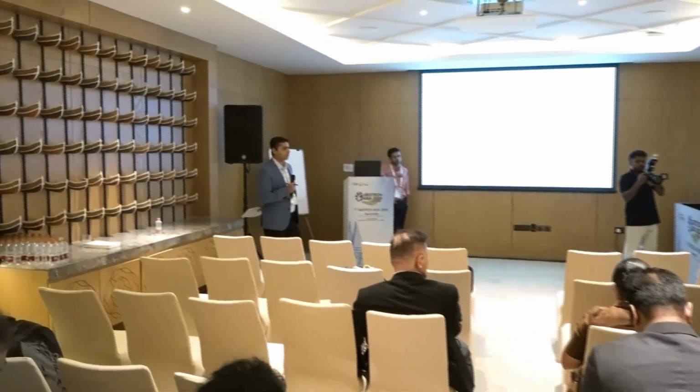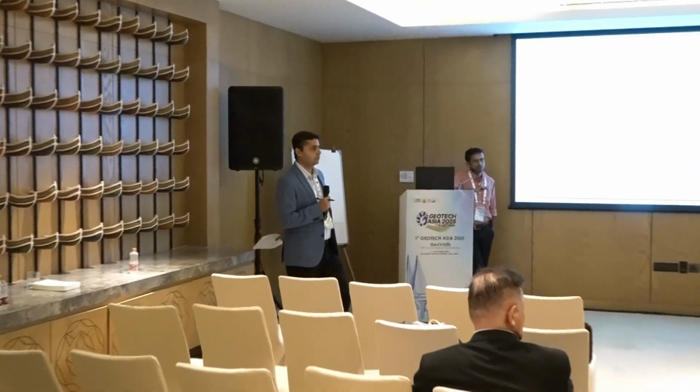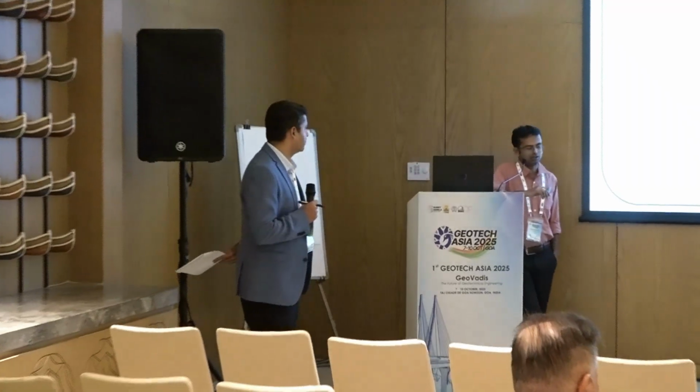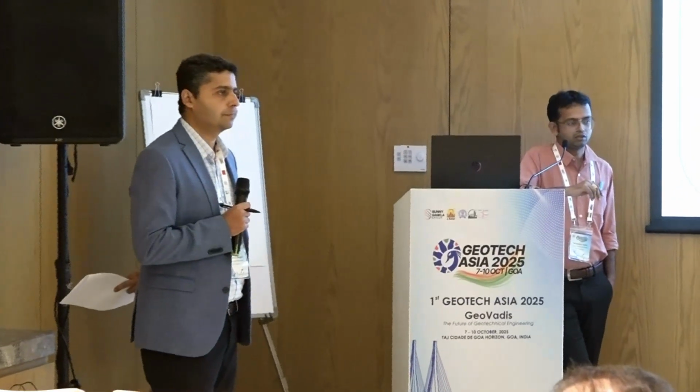Actually, to form the geopolymer, the silica by alumina ratio is important. I understand that part. The oxide results are very important, and metakaolin is used. I don't know whether in marine clay there is alumina or silica. It's there, but whether the ratio will be maintained or not, please check. And it does not depend only on the molarity. It depends on the alkali by binder ratio, and molarity is also important, how it varies. That part is also there.